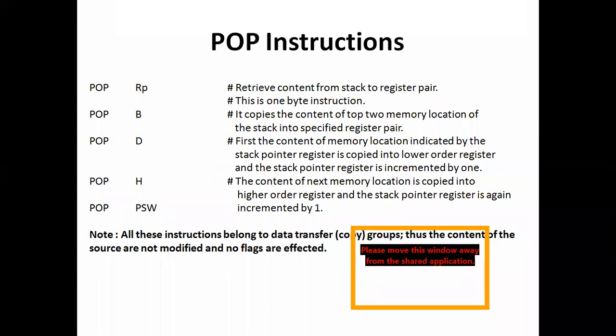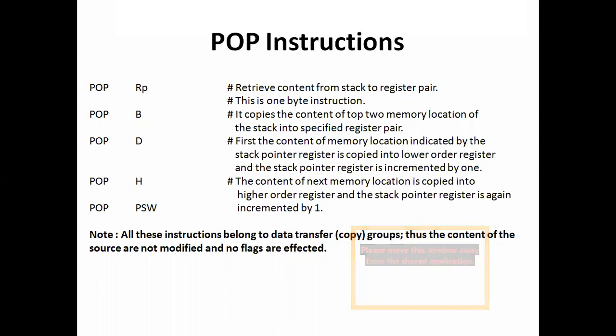Then again the copying is done, and then the stack pointer is incremented by 1. So the way we do push, we do just the reverse for pop. That is why push and pop are the instructions used for stack manipulation while writing a program.